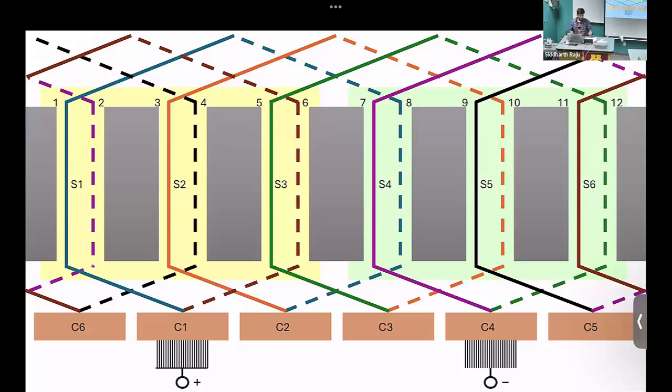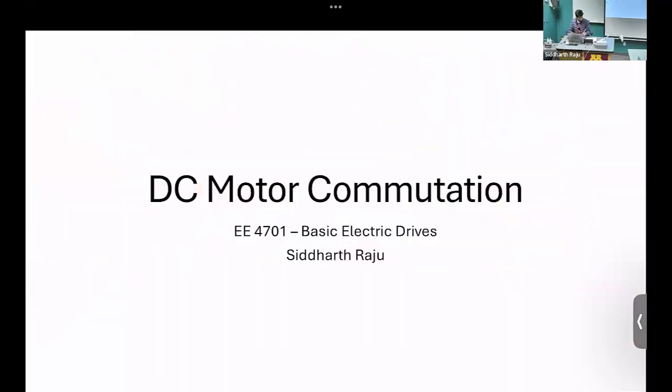So when we do a full 180 degree, so when we have 6 slots on the rotor, when we start from the first slot and go all the way 180 degree back, that's called a full pitch. Right? That will generate the maximum amount of EMF in the motor under ideal conditions. So there are other options. Instead of going one full 180 degree, you can close it off in another area, right? In which case you won't generate the full 180.